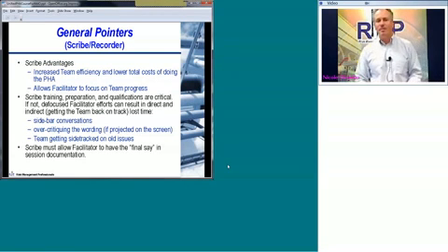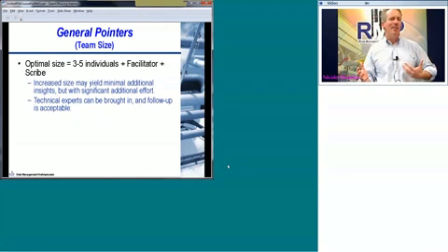Team size. I mentioned a HAZOP study with 30 people. You don't want to do that. It's very difficult to control, and it may sound very attractive to have all these people with all these different insights, but it just raises a lot of discussions about things that may not be a high priority, perhaps issues to them, but not things that help the team focus and accomplish the objective of identifying potential design weaknesses. As needed, you can bring in other people. You can start with a reasonable team that you can control, and if you need specific expertise, they can be brought in.